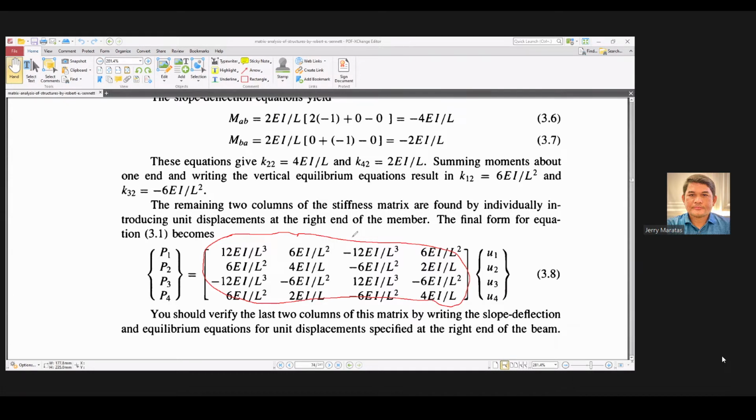Okay, the good thing about the beam in comparison to frames is that your axis is defined. It is only one axis, unlike in a frame, which is like a truss, where you have to do some transformation because you have to be consistent with your axis. So you need the global stiffness matrix, in terms of only one reference axis.